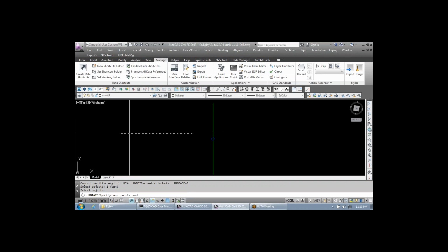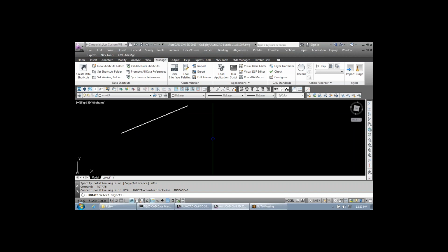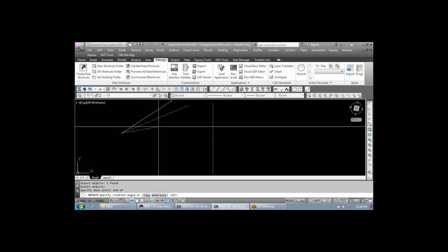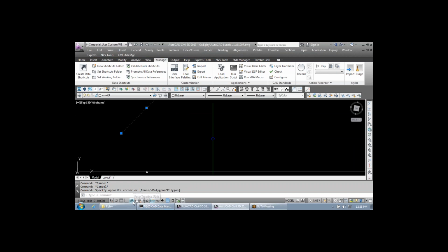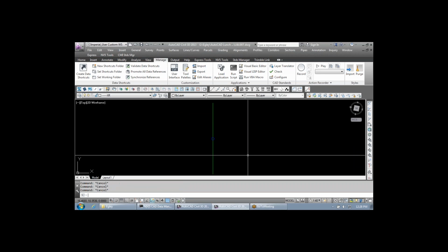What this would be used for, though, is if you wanted to rotate this guy, let's say you're working on some water lines and you wanted to work on your fitting angles, this would be an easy way of doing it, that it would snap to that 22.5, and then you could snap to the next one, 22.5. So it just might be useful to you guys, something to keep in mind. Polar tracking isn't really used too much that I see. So just wanted to bring that to your attention, that you do have some flexibility in terms of rotation angles using that polar snap functionality.